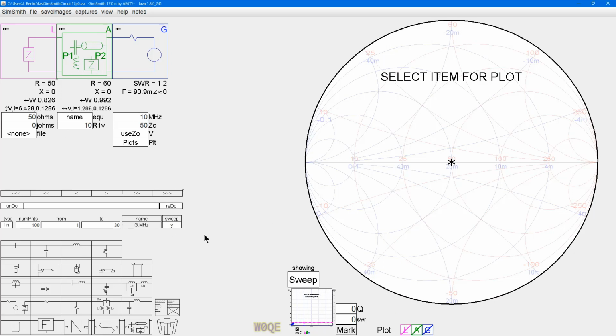We are going to sweep versus frequency, and we can change what frequency we sweep over. We're going to look at the load. And what do we see for the load? Well, we see this pink dot, 50 ohms. Well, 50 ohms is what the load was. The load didn't change. This could be a file we loaded. We'd see a sweep here of what the file values were versus frequency, but in this case, it's a fixed load.